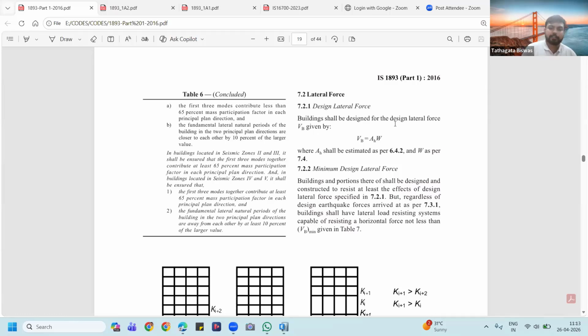Now, the static method of earthquake analysis is basically dealing with the codes. The code has a specific methodology, specific time period, specific formula through which we can create the static method of analysis. What we are trying to capture is the effect of those infill wall panels as well. Because if we just model the beam, column, slabs and shear walls, and do the analysis and design directly with that model, this particular wall stiffness would not be a part of it. Okay, it will be ignored by default. So that should not be done.